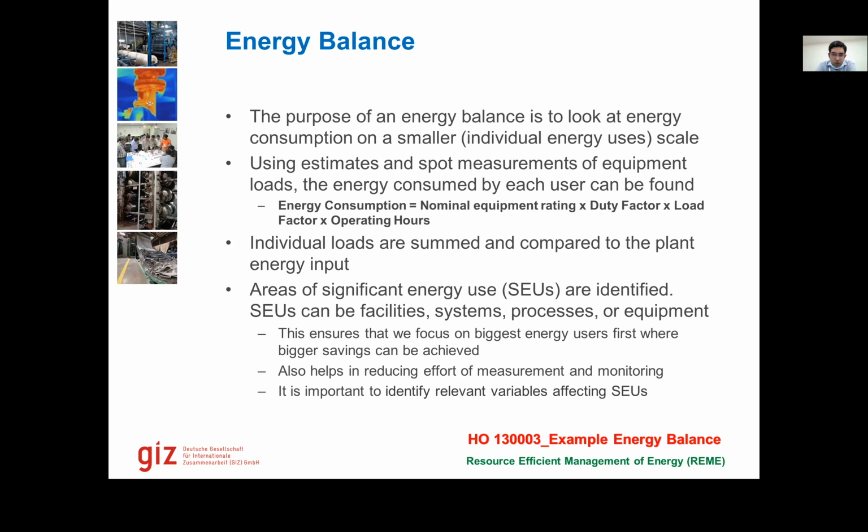Obviously, another way is to do the measurements. If we can do a spot measurement, let's talk about electricity. We say a certain motor is usually running at 4 kilowatt load. But is this motor always running, or does this motor's load also vary? So we also need to identify that load factor.